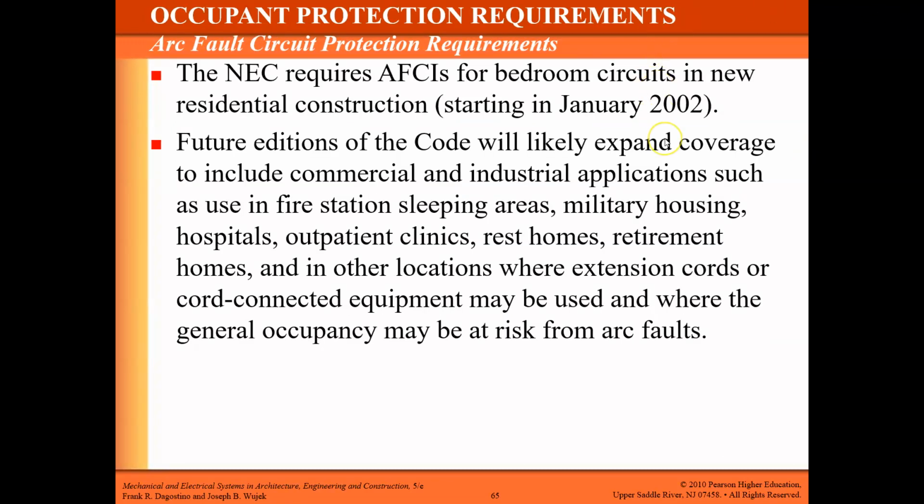So in 2002, the NEC required AFCI, and just as a reminder, GFCI is protecting against ground faults. So when the electricity leaks out, for example, into a person, it's going to trip. An AFCI protected circuit is arc fault circuit interruption.